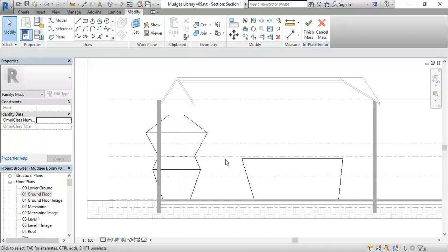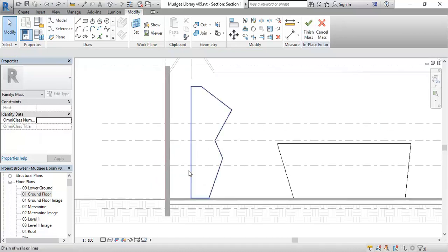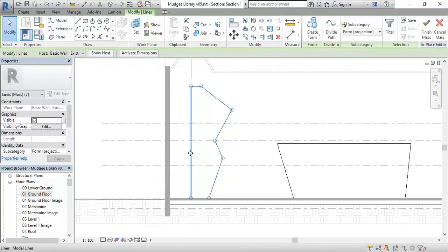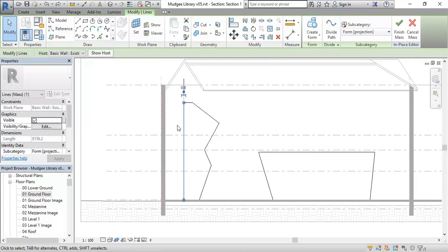It knows to make it a revolve because of the things I picked. So again, if you draw an open shape like that, just a line, usually it'll use that as an axis automatically. It knows. Okay, so it takes a bit of practice, and you'll work out the ways of making 360. I'll show you the angle setting in a moment.